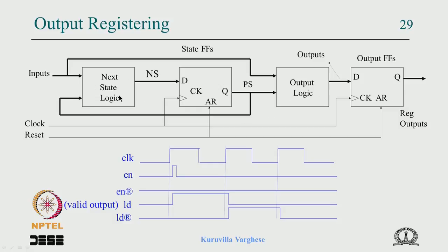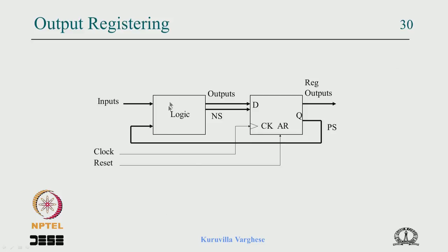this state here. Now if you look at this diagram, this stage and this stage look identical. So you can take this output logic, put it here and call it logic. Now these flip flops and these flip flops are the same, you get the same clock and asynchronous reset. So we can combine this, combining the output registering as well as the state flip flops. So that is what is shown here. Now with the output registering,